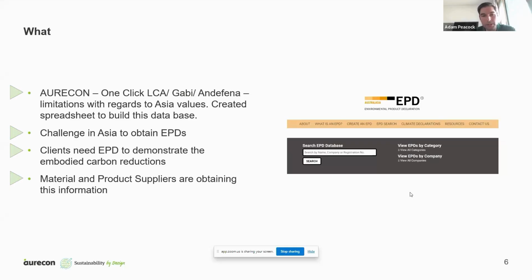And then also trying to ensure that we're getting consistency in EPDs across the whole industry. So, for example, if one supplier has got an EPD that only considers A1 and another supplier has A1 to A3 modules, which I'll go into in a future slide, there can be complexities there getting comparable results between them, so a like-for-like comparison. And a lot of clients, when they're looking to get sustainable outcomes, they need to have realistic EPDs on their projects.